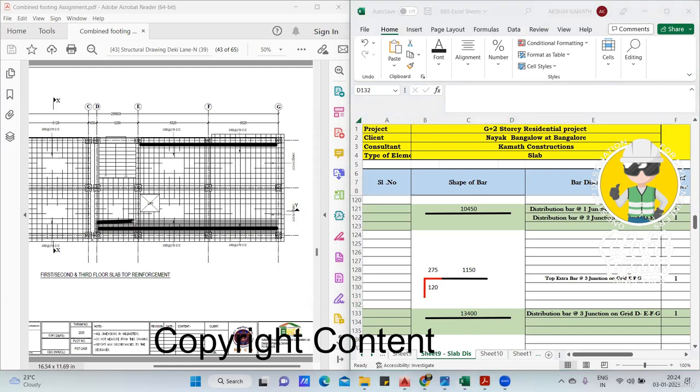From here to here, it will be 1. Then again from here to here. Since it's a cut bar, there's no point in lapping. Since we calculated everything at once, we are getting it beyond 12 meter. That is why a lap length will come. So what we can do is we can include the lap length. But again, practically if you see on the site, they won't cut. They'll take a straight bar only. And then maybe one part, they're going to do a lapping.